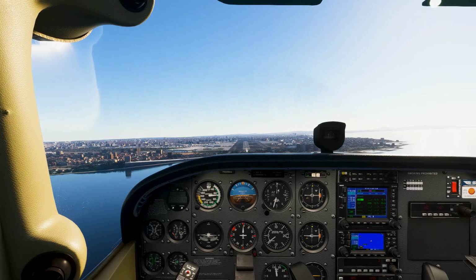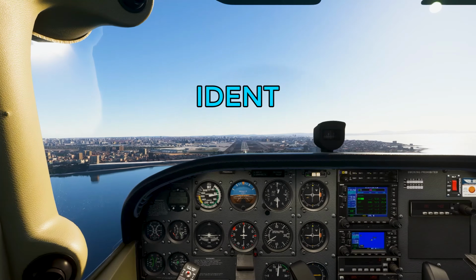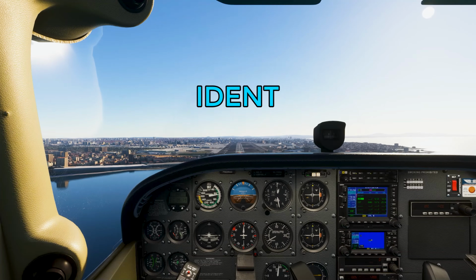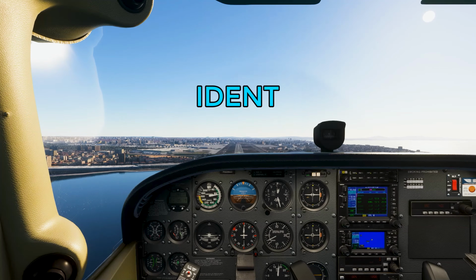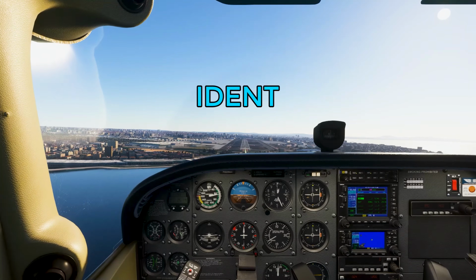Okay, so we've talked about transponder modes and transponder codes, but there's one more transponder feature you need to understand. It's called Ident. When ATC asks you to ident, they're requesting that you hit the ident button on your transponder. When you do this, your transponder sends out a specific signal that makes your aircraft's position and squawk code more prominent on the ATC radar screen.